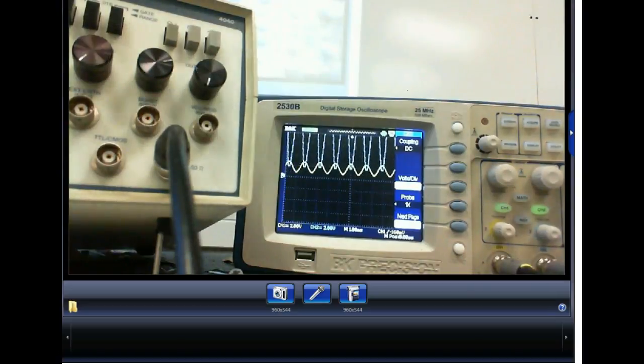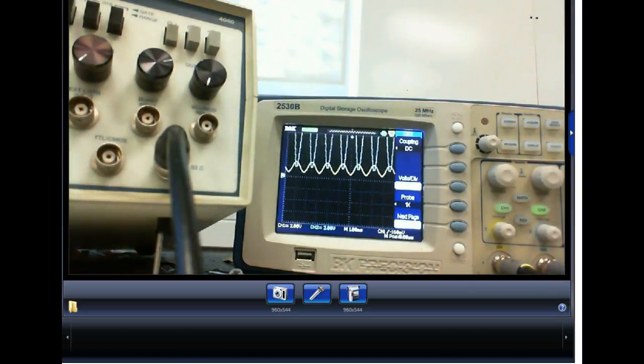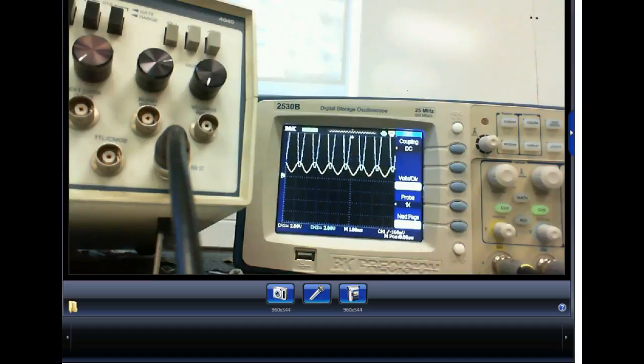So you can see inside the transistor amplifier itself, all we're doing is changing these bias levels, right? You understand? So what we end up with is AC actually superimposed on the DC bias. Does that make sense? And what do we do? Well, what do we do to get AC into the DC bias and get AC out of the DC bias? What do we use? We use capacitors.